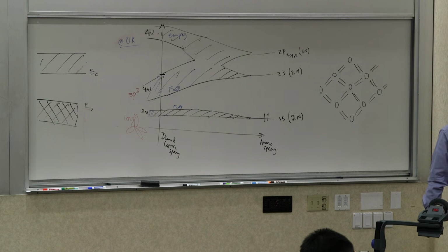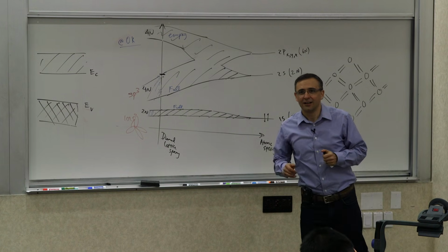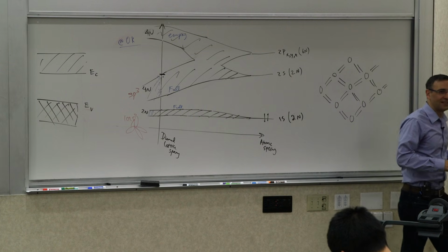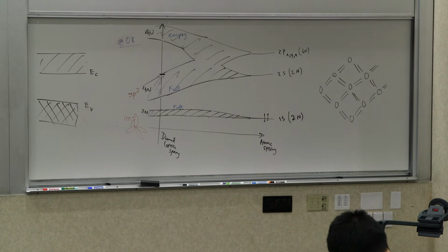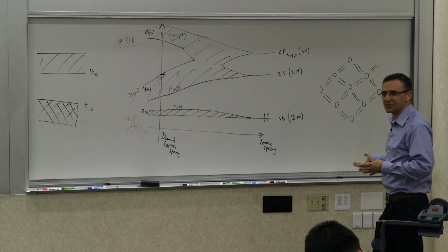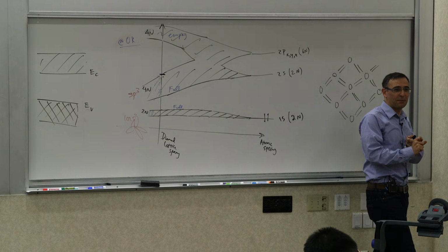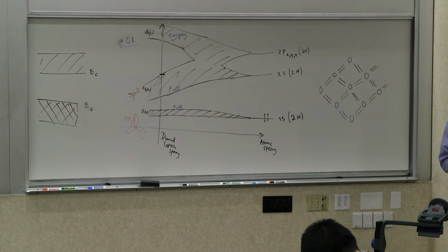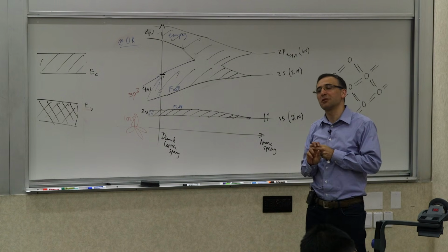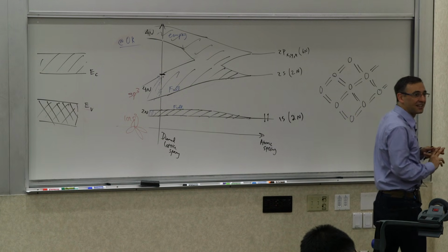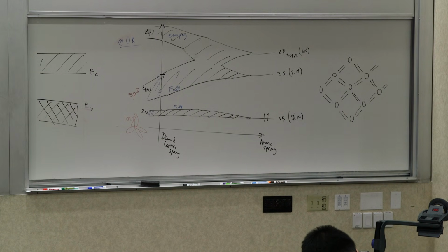Diamond actually is special in so many different ways. Not the fact that it's an artificially highly priced item because there's a monopoly on it and they throw away 90% of it. The main reason is that it's the best thermal conductor out there by a large factor. If you're really looking for a really good thermal conductor, diamond is your thing, especially if you are looking for something that's an insulator too.